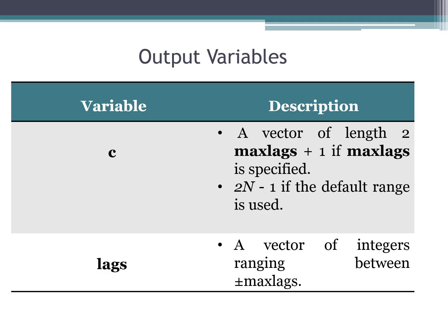Another important point to remember about the Xcorr function is that it does zero padding. In case one of the waveforms is shorter than the other, then the shorter waveform will be zero padded, so that the two waveforms are of the same length.